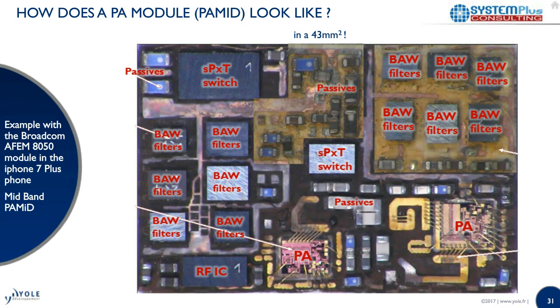You would find power amplifiers, which are wire bonded, which first sounded surprising to us, but we're using the wires as an inductance to tune the signal. You would see some filtering, some passives, really taking a lot of space on the different boards. You would see switches and the RFIC, the control mapping. So a very highly complex module.